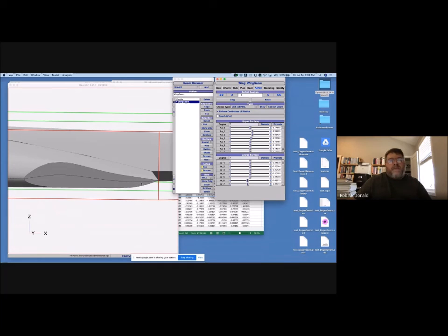Having this rather distinct upward curving camber at the trailing edge, that's what Ron was talking about as a reflexed airfoil. So normally the camber of an airfoil would be up in the front, but putting that camber up here in the front is destabilizing. But then you put the reflex in, and that makes it stabilizing. You could think about it in context of what we were just saying. I said to have a wing be stable, you needed some negative lift at the back. Well, look at what this airfoil is doing. By sloping back up, it's creating negative lift at the back. So we're creating positive lift up in the front where we need lots of lift, but then we need negative lift at the back to counteract that moment.